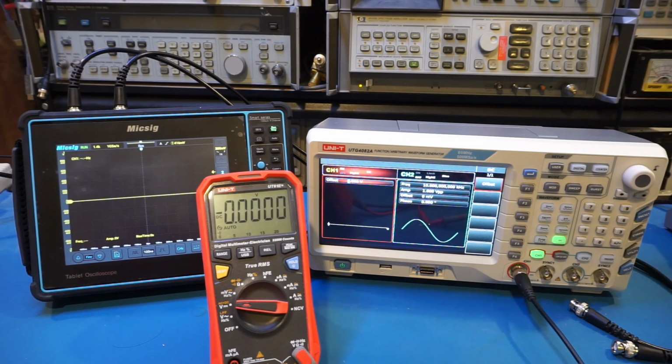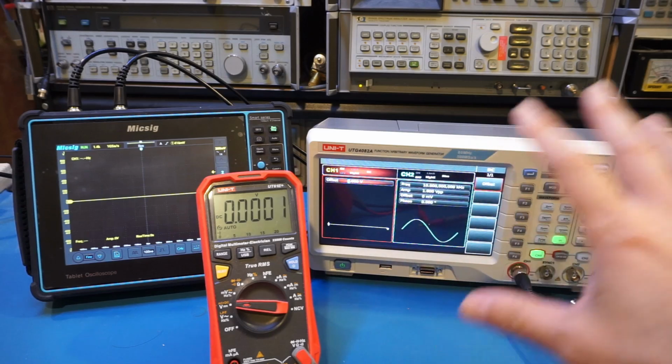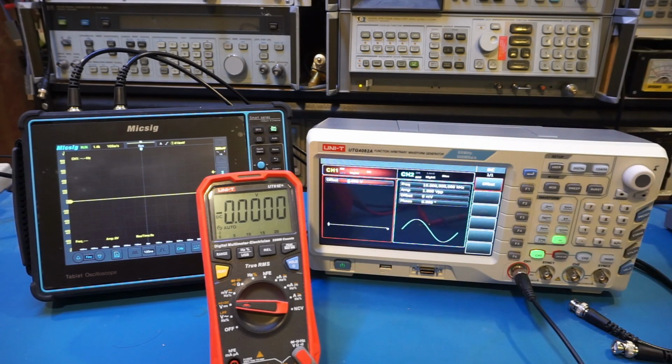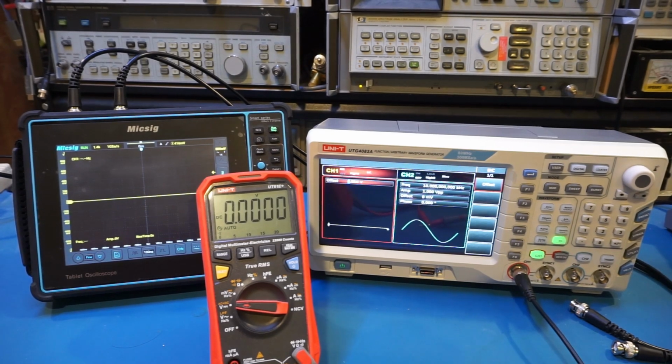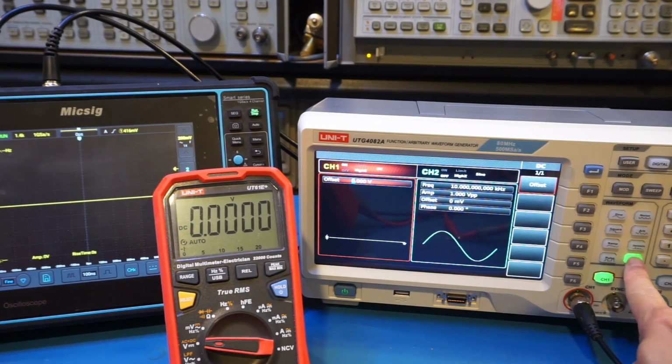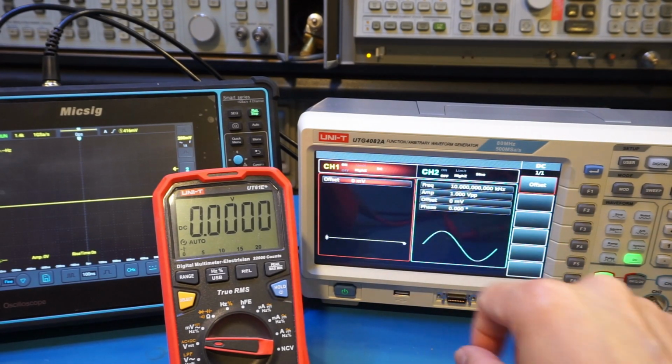The UTG4082A also supports DC output. This is a common feature on a lot of the arbitrary waveform generators, and you can use that to essentially output a DC voltage, using that as a voltage source. Of course, because we have 16-bit output, I would expect the output to be a little bit more accurate compared to the other 12-bit output ones. So right now, let me just zoom in a little bit. We have selected the output to be DC here, and right now we're outputting 0 volts.